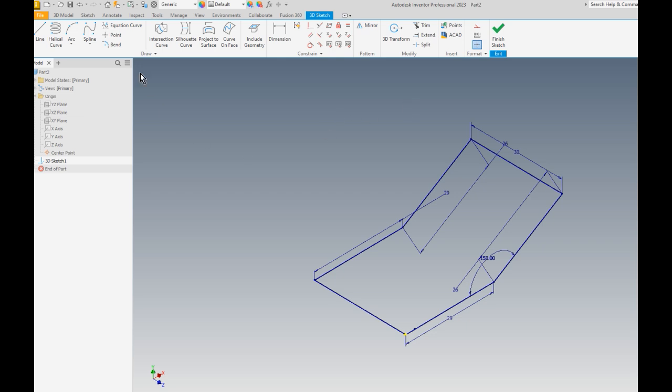Okay, I'm going to add a couple more things. The first thing I'm going to add here is a point. I'm going to add a point at the exact center of that line right here. It can be anywhere. It could be up here. I'm just picking it here just for convenience. And remember, the midpoint glyph will always be green. So if I click on that, there is the green point, and we will see why I did that in a couple of seconds. All right, so it looks good, but I'd like to have a couple more blends.